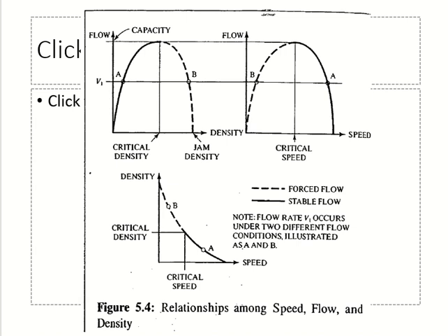And as the flow increases, that means more vehicles are on the road now, so your speed will decrease. The flow can increase up to how much? Capacity, right? You call this point capacity. And I told you the graphs are overlapping. So if the maximum flow here is capacity, the maximum flow here is also capacity.